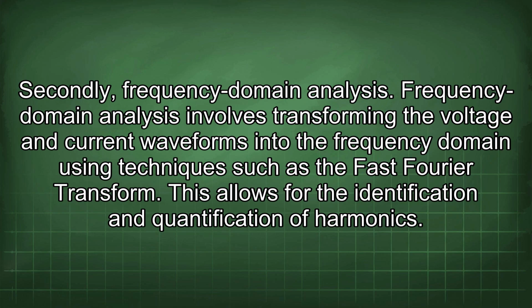Secondly, frequency domain analysis. Frequency domain analysis involves transforming the voltage and current waveforms into the frequency domain using techniques such as the fast Fourier transform. This allows for the identification and quantification of harmonics.